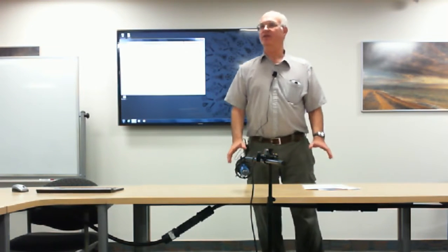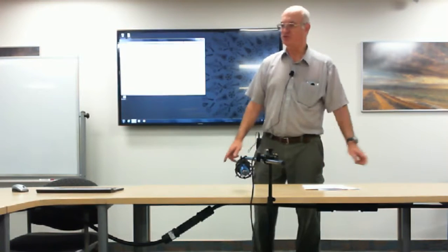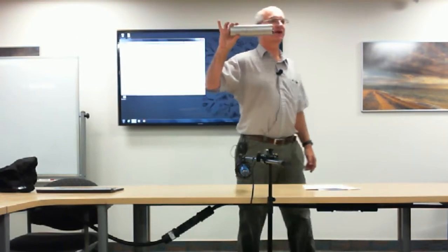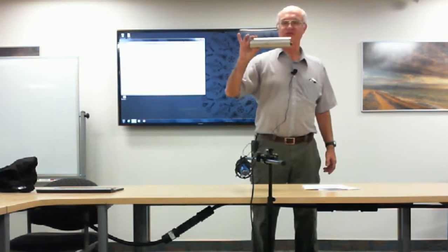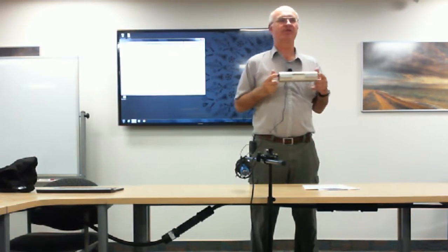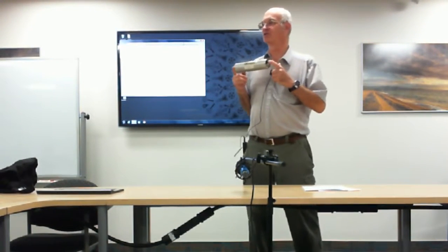So again, what you want to do is get rid of this at the source. To do that, I highly recommend that you never set up an HF radio station without installing one of these and keeping it in the line permanently. This is called a low-pass filter. This will block all the harmonics above 30 megahertz. So you can run an HF station knowing that you're not putting out 54, you're not putting out all these other frequencies. And this will probably save you a lot of phone calls.